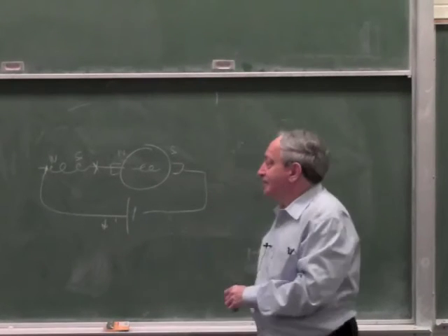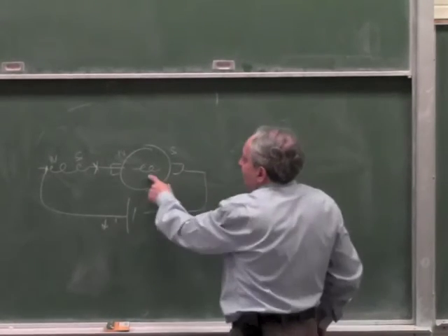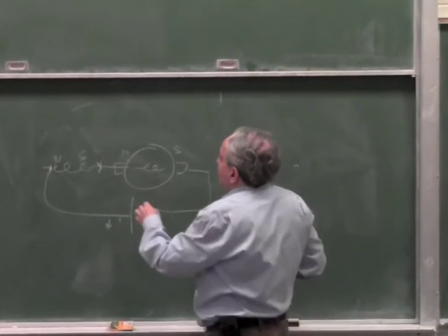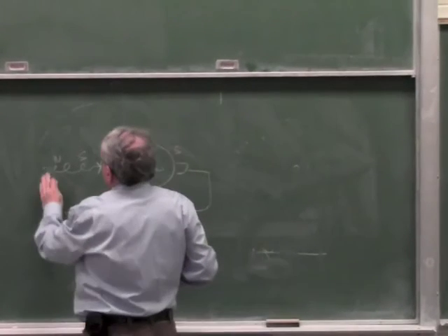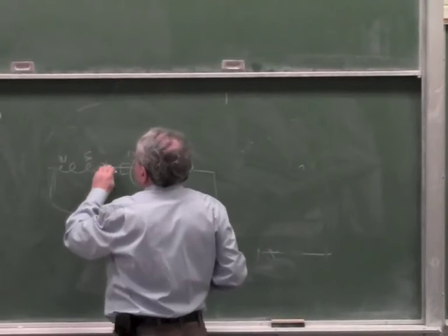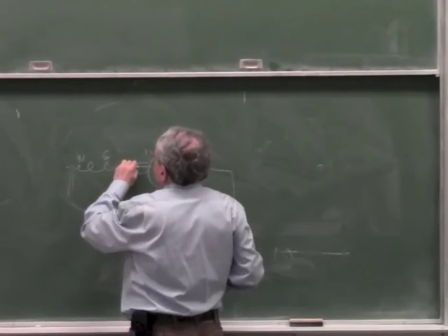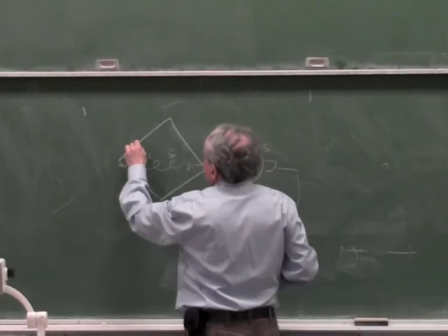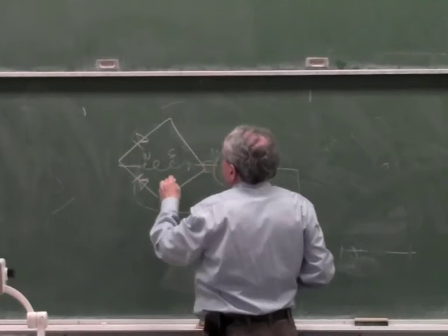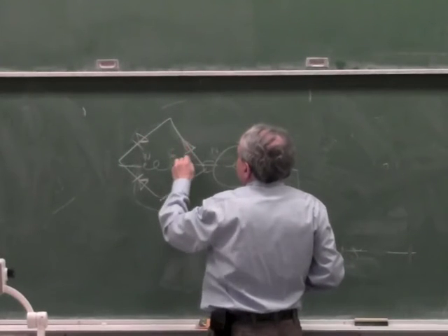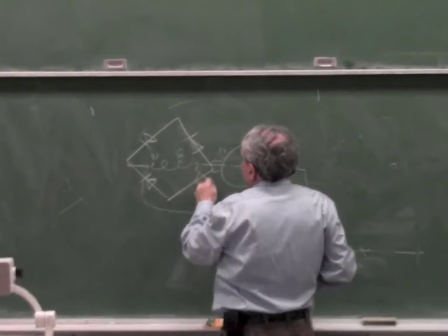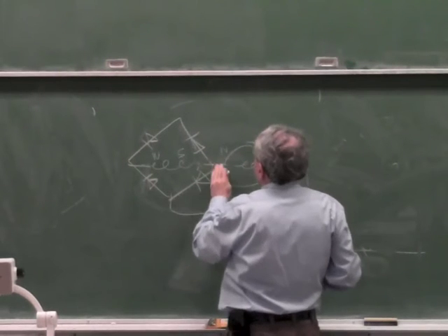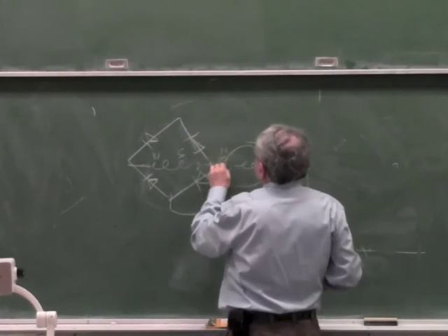Perfect. Very good answer. All you have to do is put this in a rectifier, so this will see the same direction. Imagine if you put the coil in a bridge rectifier. A bridge rectifier is something like this. It has 4 diodes. That's a standard bridge rectifier. Like this. And now you connect the power here and here.